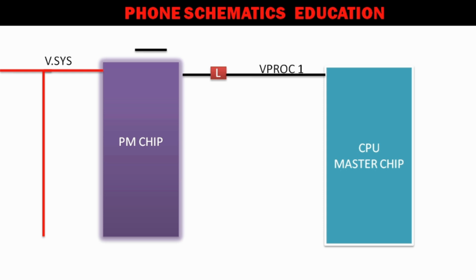We're just talking about this line. In schematics, I'm also showing you in a bitmap. Right? Now, after this, another line emerges from this line and goes back to the power IC. We call it a feedback line. We see this in schematics, right? Now, in this line, you get 0.6 to 1.2 volts.